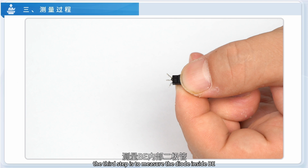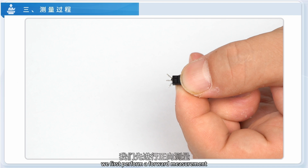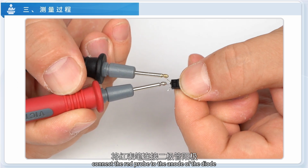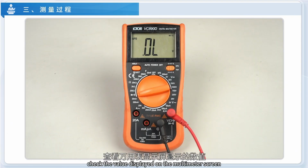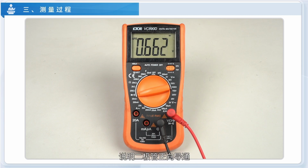The third step is to measure the diode inside B and E. The steps to measure the diode inside BE are the same as for the internal diode of BC. We first perform a forward measurement. Connect the red probe to the anode of the diode and the black probe to the cathode. Check the value displayed on the multimeter screen. The value is between 0.1 and 0.9. It indicates that the diode is forward conducting, which is normal.